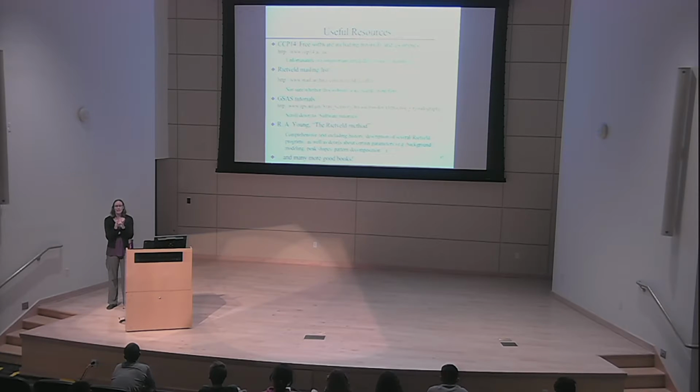So the full width at half max, some of that is just basically taken into that. What we then basically do is we plot the full width at half max we see for the standard as a function of angle. And in most cases, that is actually a very simple function that we find. Often over the range that we extract peaks where we can extract single peaks, we basically see something that stays close to constant.